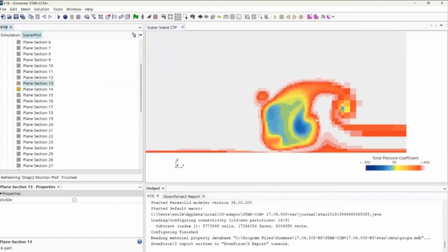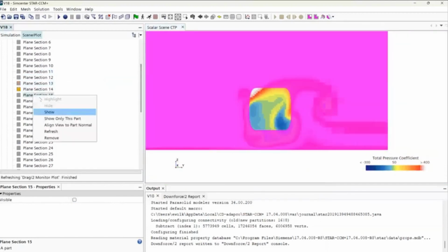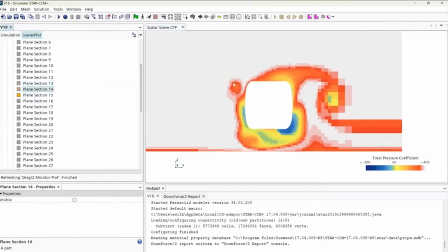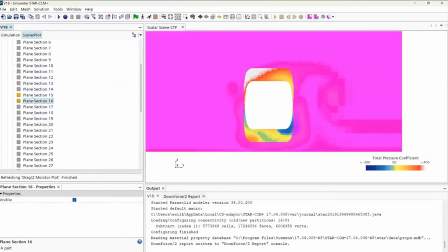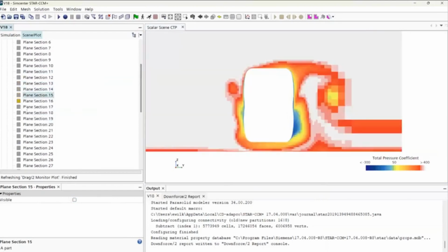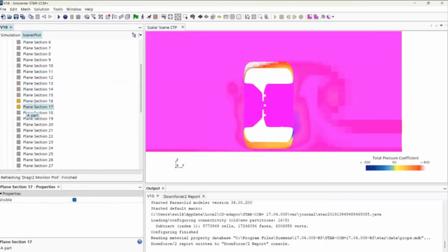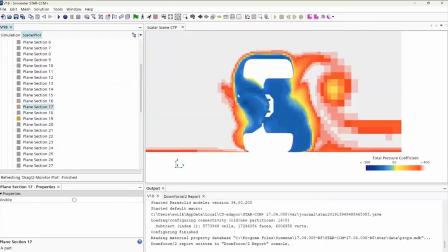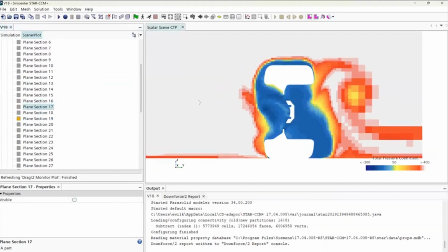But you're hitting the tire now. Now you're at the tire. How is the air reacting? How is this vortex reacting? Spoiler alert, it gets destroyed by the tire. Well, eventually it does. Yeah, the vortex is gone now. But you have this inward vortex, and you can see the difference. And of course, this is consistent with what we saw in turbulent kinetic energy.